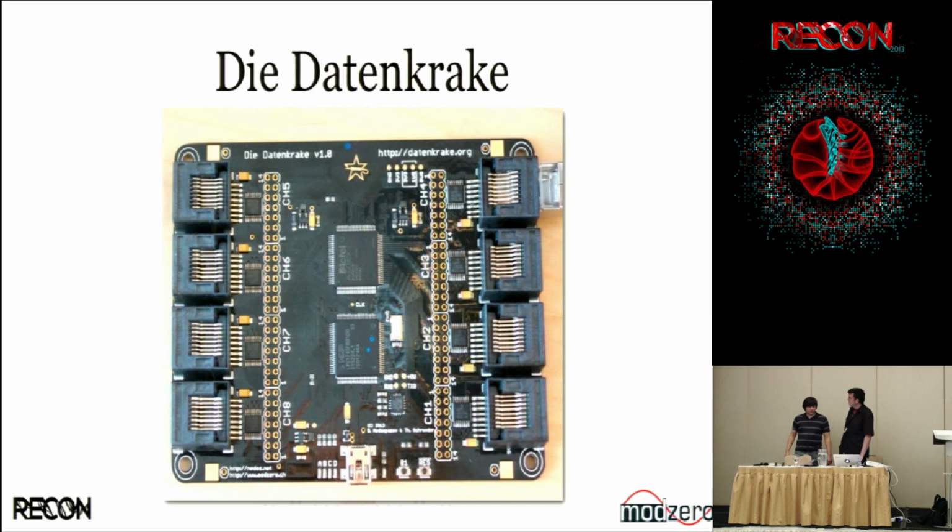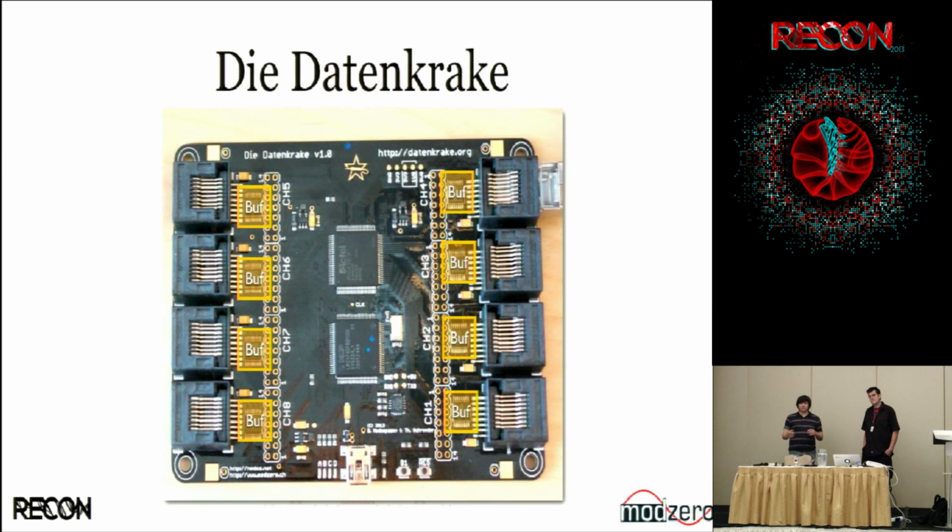The next thing we have here should be the buffers. You can see we buffer the signal. This is mainly just to make sure the FPGA is protected, since it isn't as tolerant as certain other things, but these buffers are definitely 5-volt tolerant, and they should also work at lower voltages. As far as I remember in the datasheet, it should work at maybe 2 or so. I haven't had that much time to try it out, but in general, the FPGA spits out 3.3 volts, but you're not going to blow it just by connecting it to 8 volts, which would be the case if you directly connected to the I/O. So worst case, you blow one of these buffers, which are easy to replace and fix.